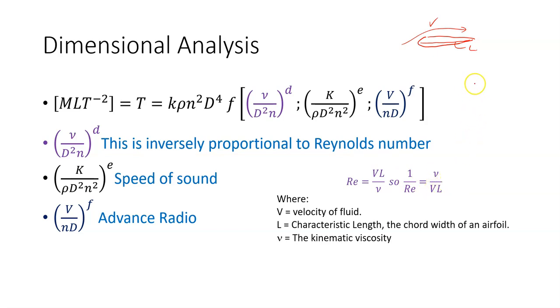And if I have a propeller blade, the air coming in is that way, and then this is the air due to rotation, and this is the airflow over the propeller. So it is proportional to this omega r. Okay, so the velocity is proportional to this omega r, and omega is just radians per second.